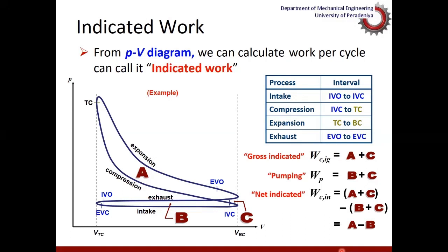There are a lot of cycles. If it is a two-stroke engine operating at, for example, 60 revolutions a second, then 60 cycles will be created. And if it is a four-stroke engine rotating at 60 revolutions a second, the four-stroke cycle needs 2 complete revolutions to complete the cycle. Therefore, there will be 30 cycles in a second.